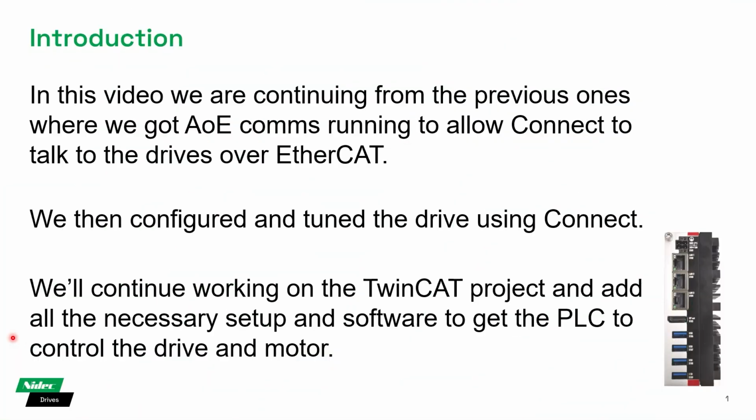Hi, in this video we're continuing on from the previous ones where we got ADS comms running to allow Connect to talk to the drives over EtherCAT. We then configured and tuned the drive using Connect. We'll then continue working on the TwinCAT project and add all the necessary setup and software to get the PLC to control the drive and motor.